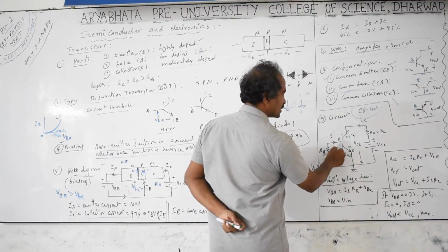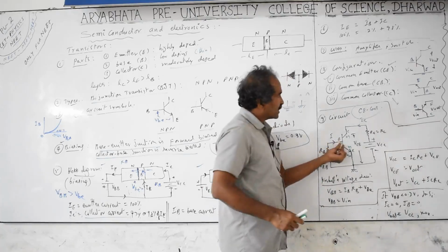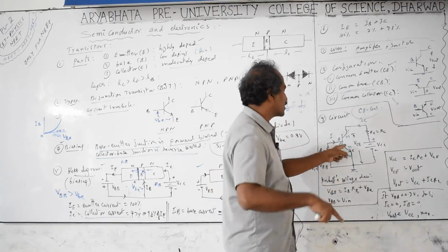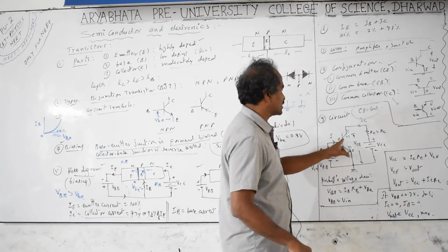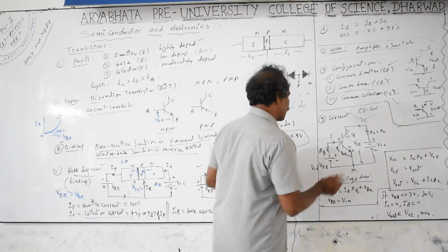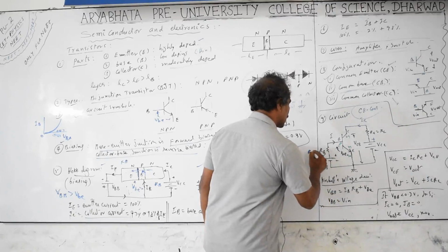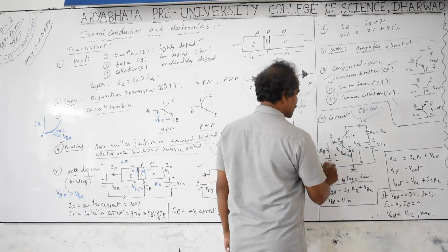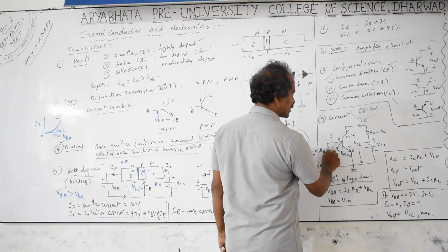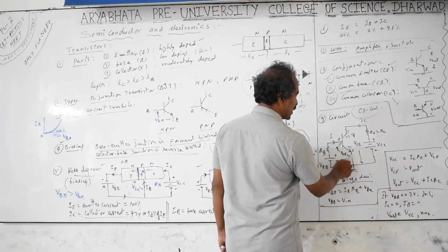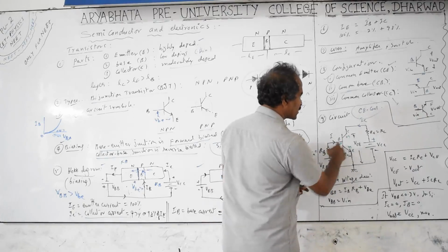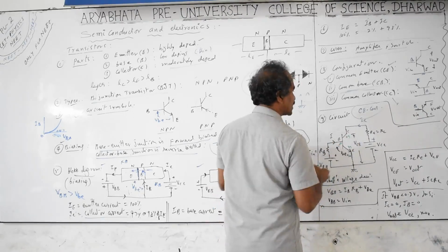Sometimes the metal of this transistor material at the base also has some small, very negligible resistance, which you would have to take in series with RB if it is given, but that is neglected. So this RB itself we take as Rin, called the input resistance. This base bias voltage VBB must be greater than VBE for the current to pass from the base to the emitter. Whenever this current passes, it is like a closed circuit. Whenever it is closed, the collector current IC also can pass.